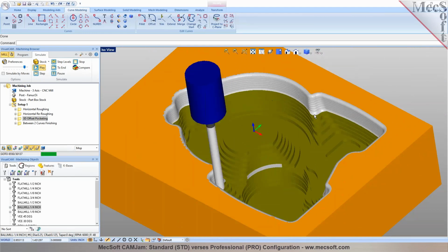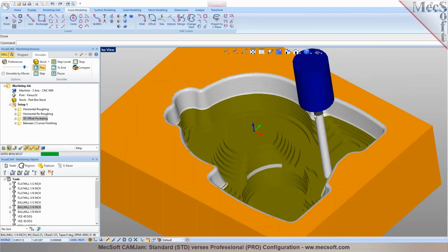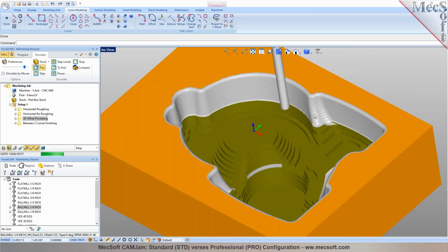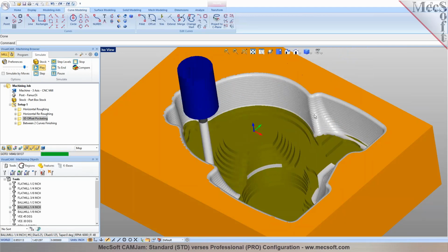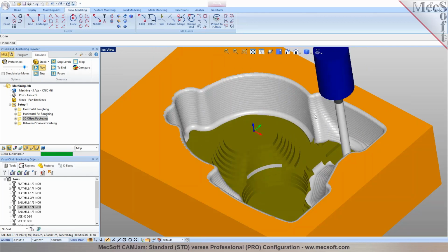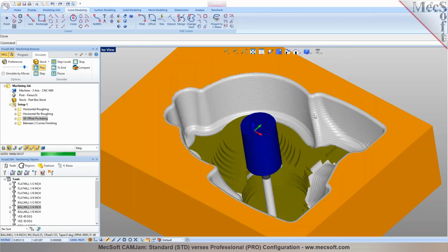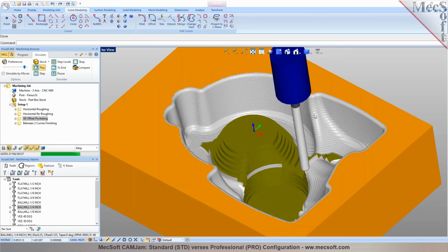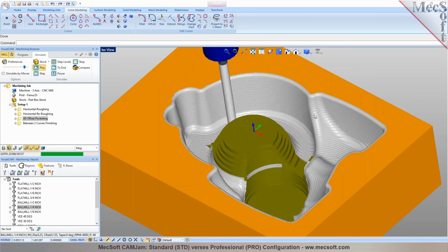Okay. So rather than having to do a horizontal finishing and a parallel finishing, a combination of the two, you can do your outside edge without doing the entire part. Seems like it's probably more efficient. Right. So you have more options, more techniques for finishing.